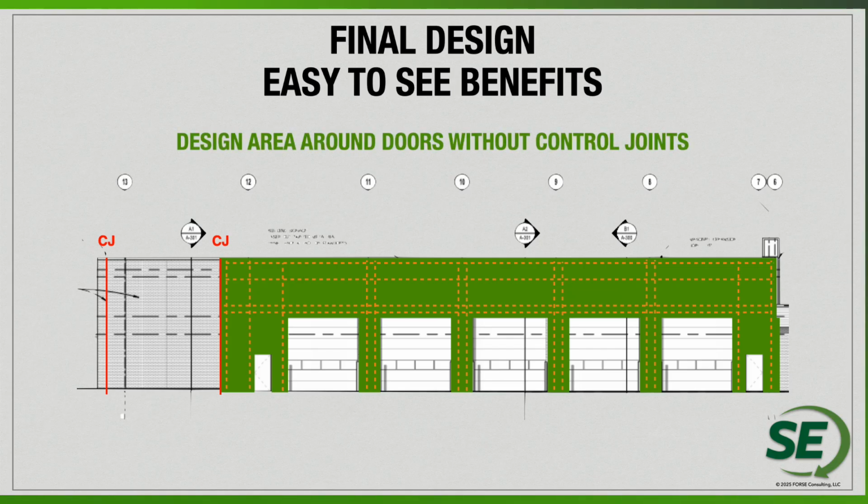Certainly you can go back to the areas outside of the openings. If you're in a lower seismic area, it's probably beneficial to go back to the large walls. The shear capacity is going to be fine for a large wall without any openings, but elevations with a lot of repetitive openings can benefit from moving those joints away and utilizing continuous lintels and a much better in-plane shear capacity due to really having basically a moment frame versus wall elements.